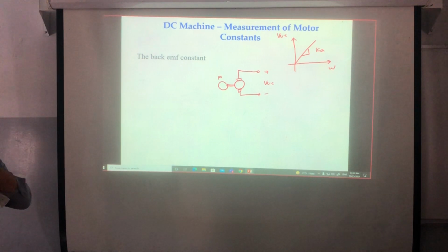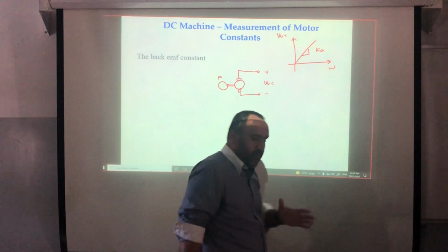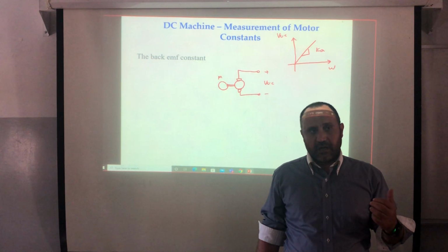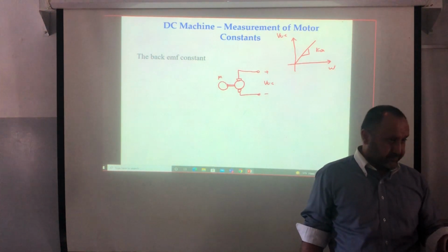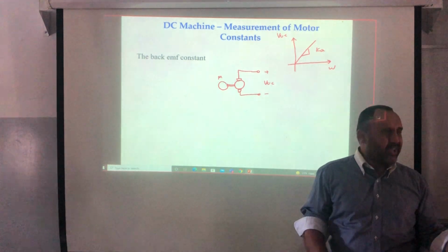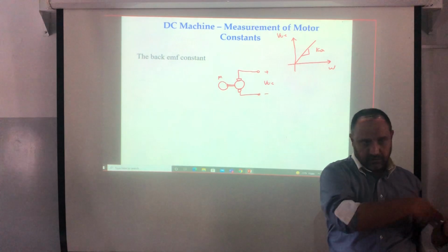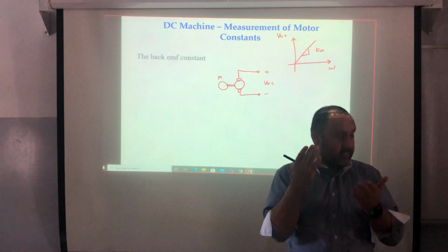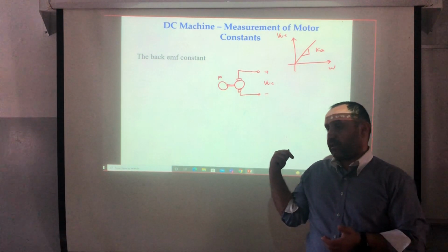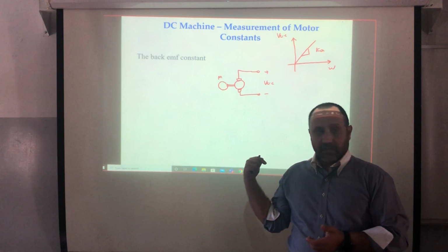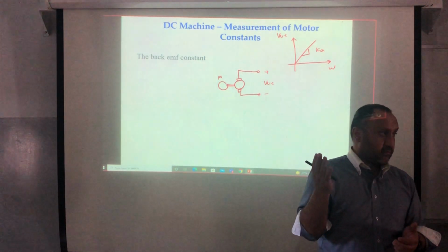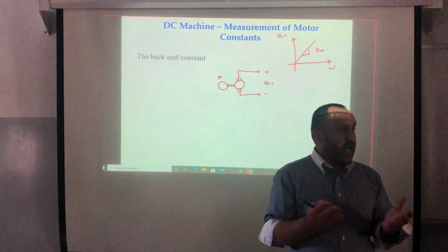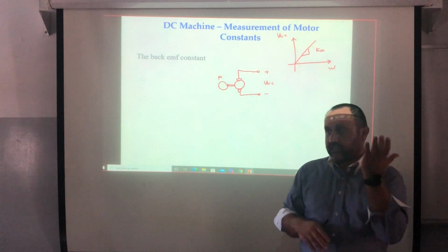Now, do you remember, Sliman? Recall that if I'm using precise current control, or PI current control, in the end of the day, I'm using PI current control. Why will we use PI current control? Because the integrator will raise the type number by 1. And the DC machine, the relation between the speed and the voltage, is type 0. So if I'm adding an integrator in the loop, I will raise the type number by 1.